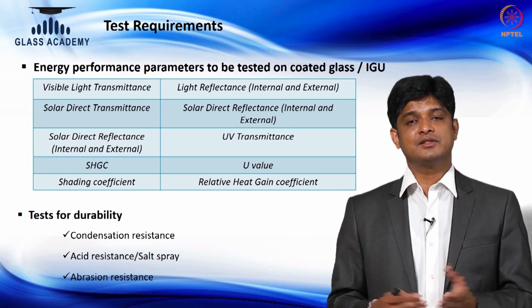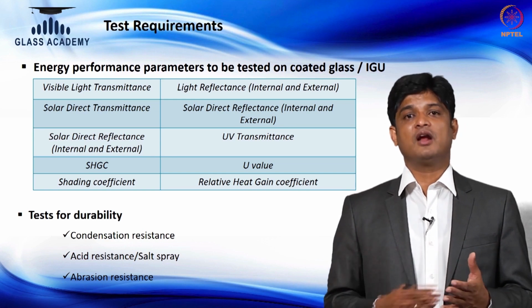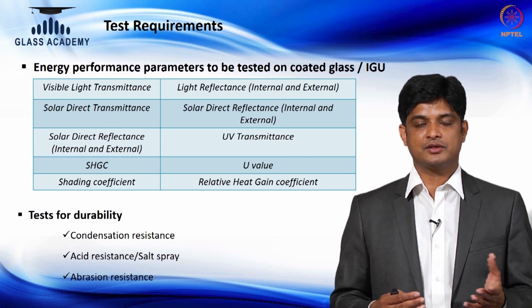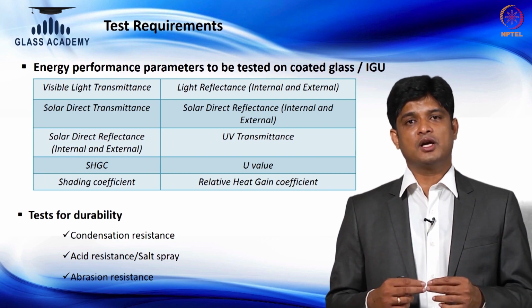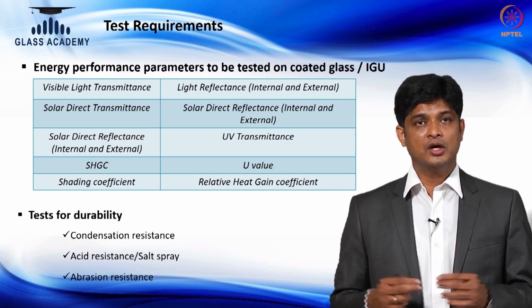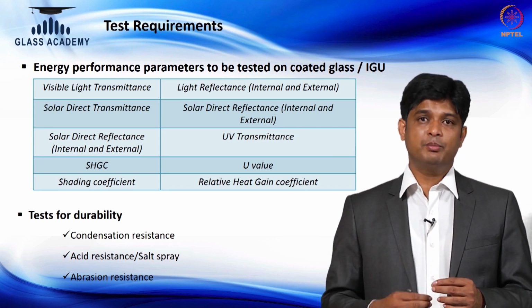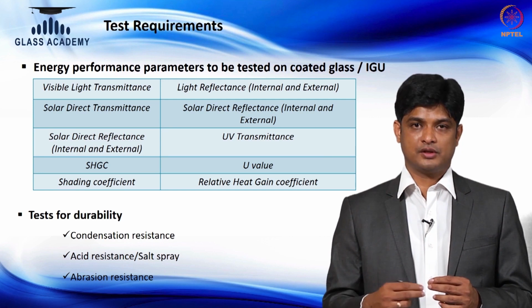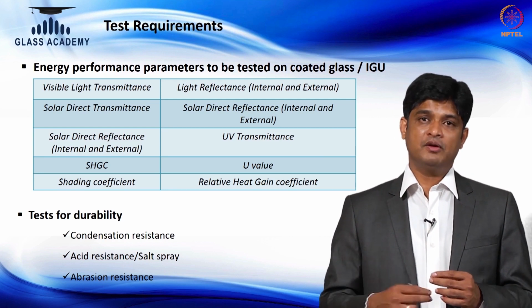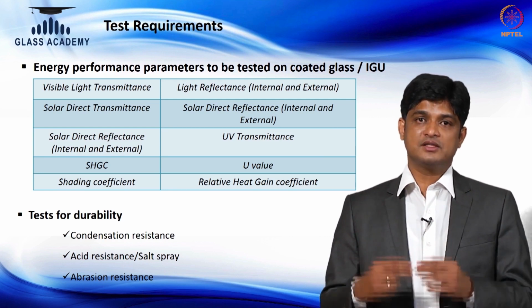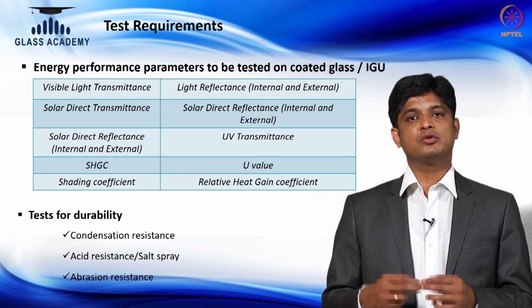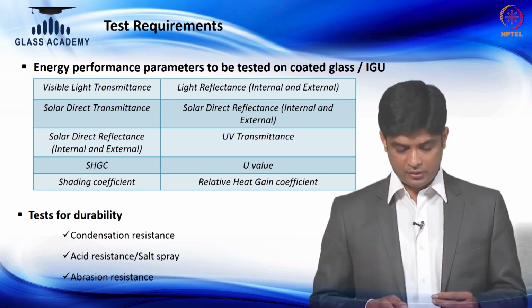If it is a single glazing, the glass goes through a cleaning process at the site after installation. So are the coatings durable enough to take such abrasion? These are the durability tests which have to be done before the product comes out of the factory, and even after it is launched. As an end user, we also have a provision to test these products in third party laboratories.